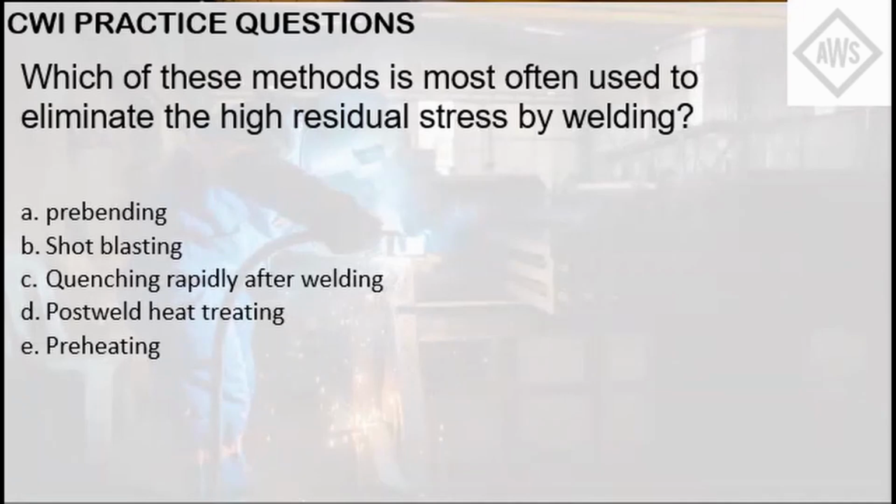Shot blasting, in the meantime, is a form of surface preparation technique used to remove debris and irregularities in the base metal. Some examples here are sandblasting. When you prepare a metal prior to welding or prior to painting, sometimes you need to sandblast it in order to remove the irregularities or debris or an external coating that is undesirable prior to welding or repainting of that base metal.